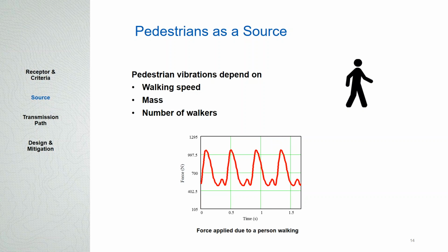Now, what's important about this is that this is a very complicated curve, and we can actually take this signal and break it down and look at the various frequencies that are excited. Because when it comes to dynamics, you've probably heard the term resonant frequency before, and that's something that we want to be avoiding as much as possible. Resonance is whenever the natural frequency of a structure, and every floor is going to have a natural frequency, or many frequencies actually, and the frequency of the applied force line up. When they line up, you get a big response, which is obviously a problem.